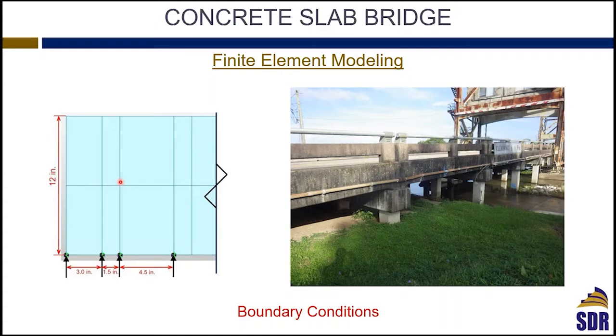Just from a structure analysis point of view, if you have a simple beam with a hinge and a roller, and with the uniformly distributed load, your moment on this beam is WL square over 8, a hinge and a roller. Just put this beam on a hinge and try to calculate your moment and see what are your vertical reactions. Just as simple as that. That's a challenge by itself.